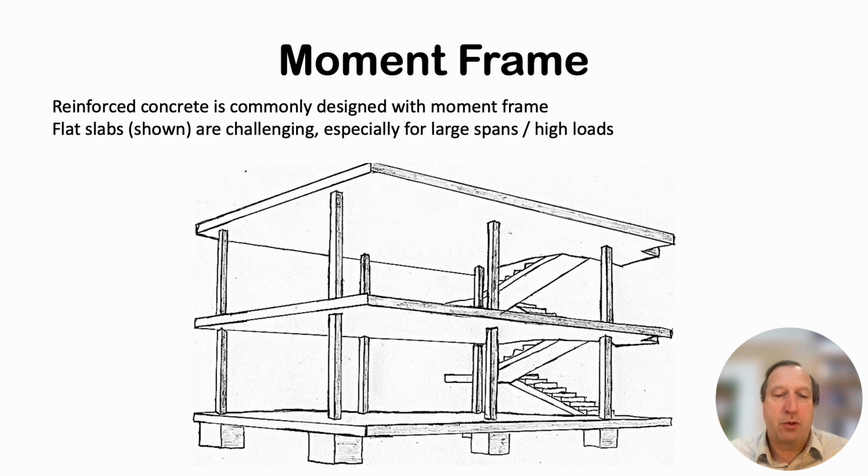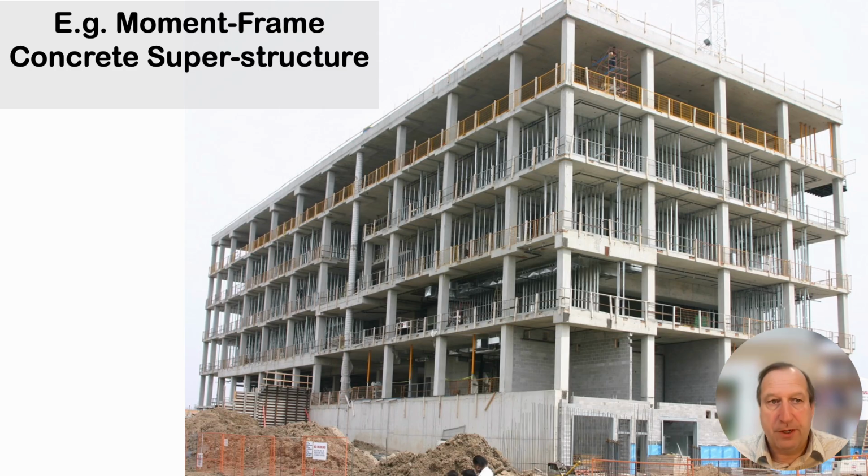Moment connections between slabs and columns, beams and columns, are relatively inexpensive when made out of reinforced concrete and quite expensive when made out of steel. It's not a technical problem. It's a trade and dollar problem. Again, here's an image from E7. Pretty clear that you can see the reinforced concrete. There are no braces. There are instead thickened connections to the slabs.